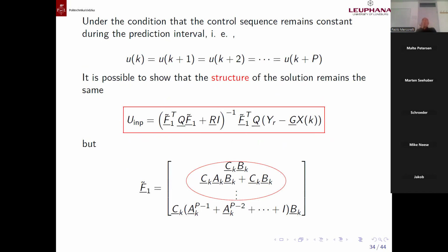Of course, this is a little bit strange. But the reason is that very often the input really changes very little. The changes are really very few. The reason is that very often the horizon is very short, and the sample time Ts is very short. This means it's an assumption which can be considered valid. Mathematically, of course, it's a little bit strong, but practically valid.